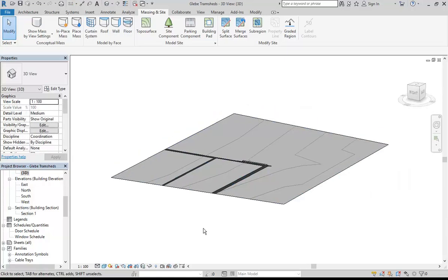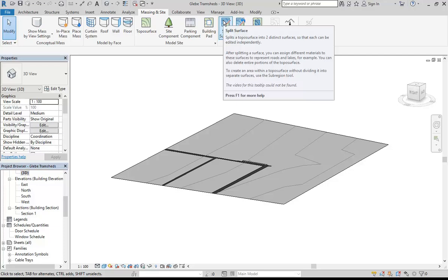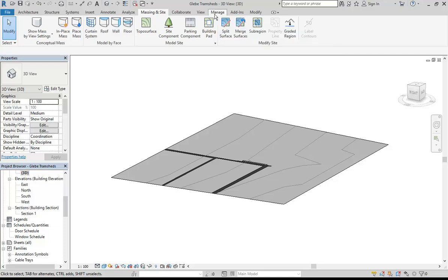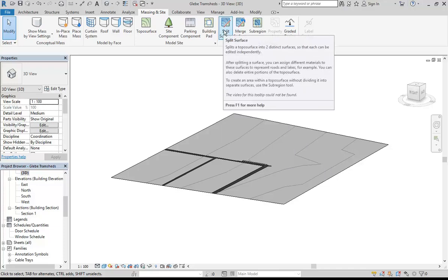But it's really just so you know that you can start on all of these things without having all the information. Can you now go to that subregion and make that like the difference, the drop? No, so the subregion boundary, no. If you want to do that, you've got to use split surface to break the surface up into different pieces. And I wouldn't recommend using that until you have to, because once you split the surface, it's really hard to put it back together.